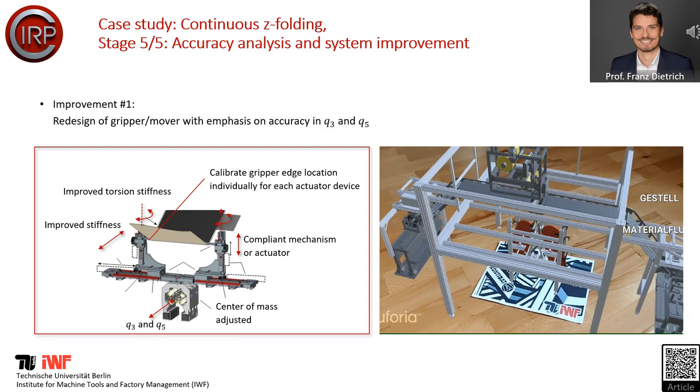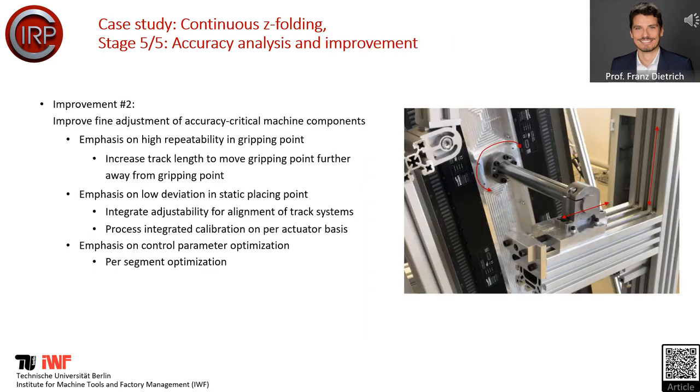And we found out that vibrations would be really significant, vibrations that occur on the basis of the really high accelerations that the system achieves. So we redesigned these movers such that the center of mass is adjusted and the buildup of vibration is minimized.